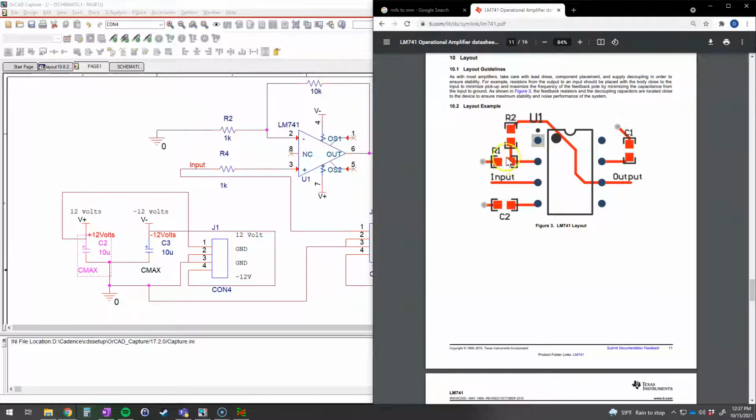These are square landing pads here. Like this is a hole right here. This is assuming that they were what are called surface mount resistors. But it doesn't matter that we're not using surface mount resistors. We can still do the same thing. We just need to account for the fact that they're not surface mount.